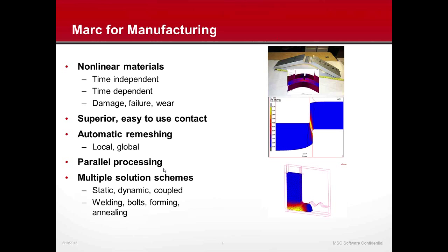And Marc's capabilities are very well suited to simulate a large number of manufacturing processes, including various types of forming, cutting, material removal, riveting, welding, and so on. And also, due to the implicit methodology that is used in Marc, the spring back calculations especially are much more accurate compared to some explicit solutions that are available for this class of problems.